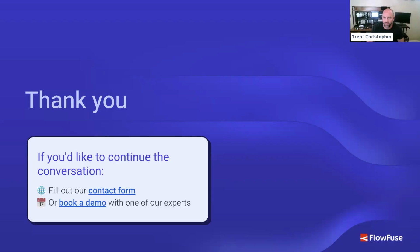Christopher asks, can FlowFuse be used as a protocol converter, such as Ethernet IP to OPC UA? Absolutely. You can use the nodes that I actually just showed you, even though you won't be reading to a Rockwell controller. If you're trying to read from one PLC and you want to copy it to the other, you can write data as well. So you can take from one data source and write to the other one. No problem there. Modbus TCP, sure. OPC UA, yep. You can read from one PLC type and then write a different PLC type. Yeah, you can do all that conversion inside the flow and then send it as it's expected.